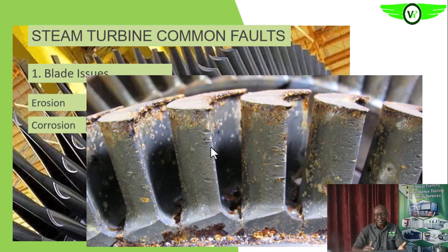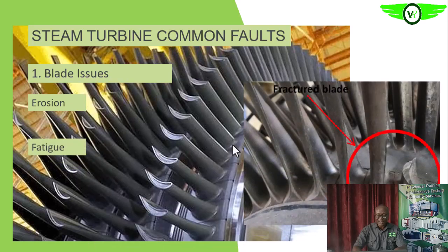We know that on the low pressure side the steam is cooler, and since it's cooler, the possibility of us having condensate around that area is high too. So that can enhance the corrosion around that area. As we'll see later, effective boiler water treatment is what is needed to avoid this kind of problem.